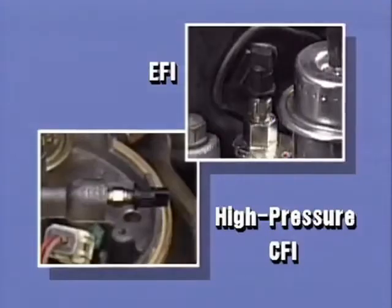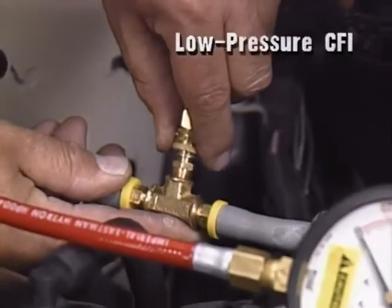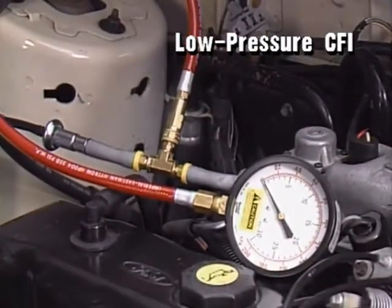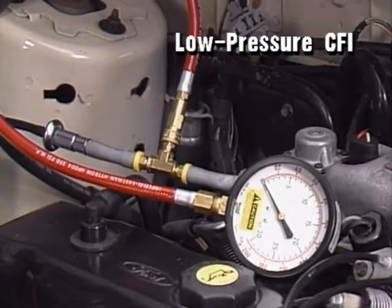Remember, EFI and high-pressure CFI systems have diagnostic Schrader valves for pressure checking. But low-pressure CFI systems don't have the Schrader valve. You have to disconnect the fuel supply line and connect the pressure gauge with the adapter.